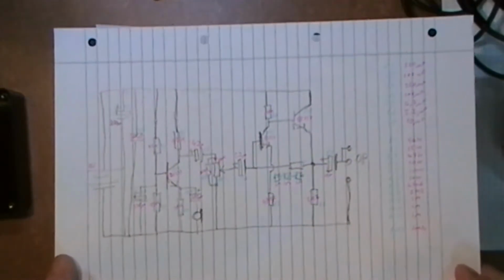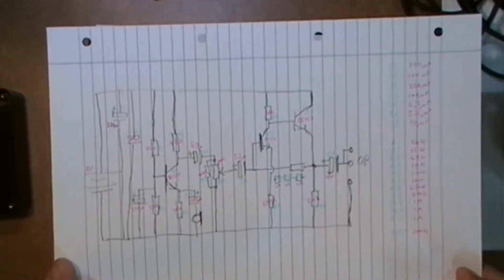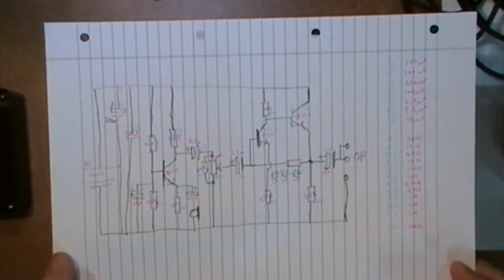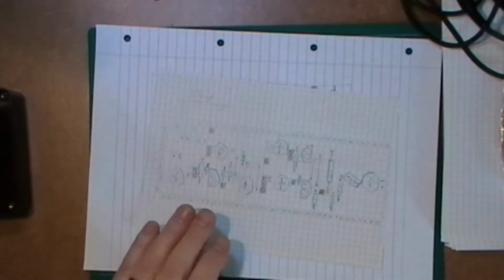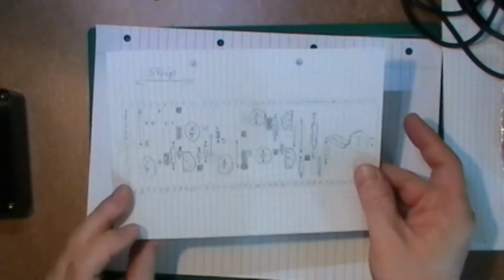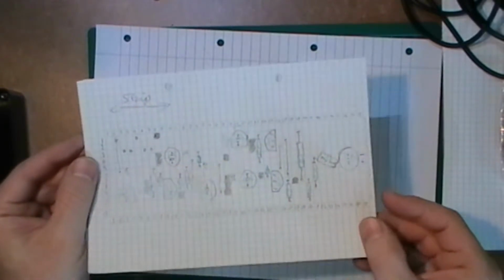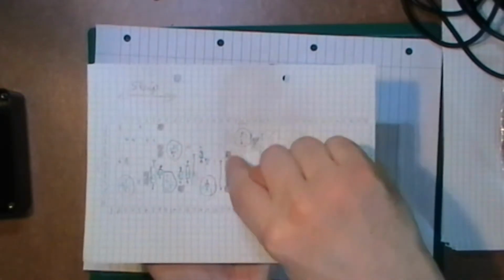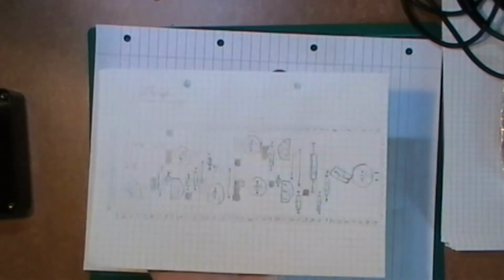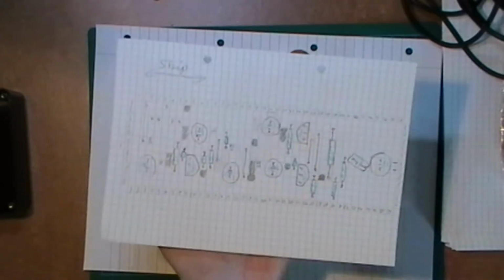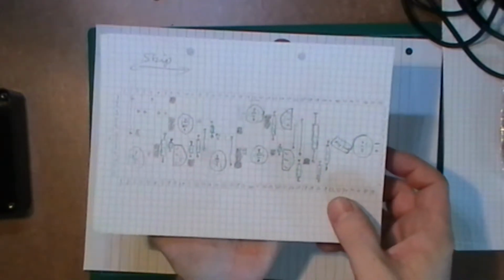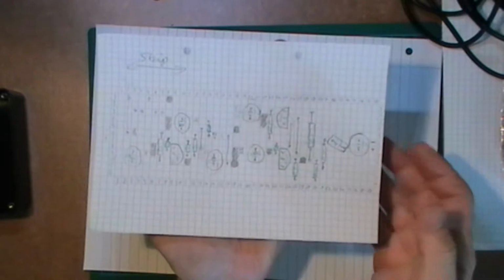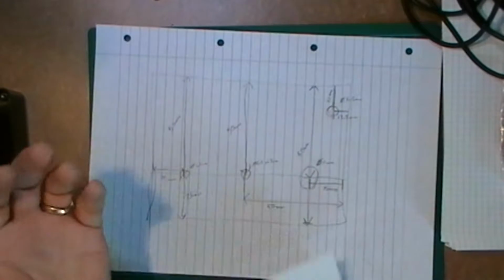It's always good to do this as an exercise, to make sure you get all the right parts and you've got all the bits you want. Then I had to work out how I'm going to put it on the strip board. So I made a sort of circuit diagram as to how it's all going to get laid out. Tracks are going to be cut and links where it's all going to sit, so I can follow that. Makes it a much quicker exercise than trying to do it ad hoc as you're going along, because then you end up with stuff all over the place where you don't necessarily want it.